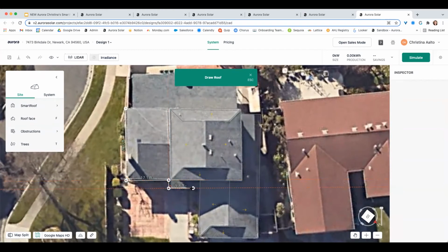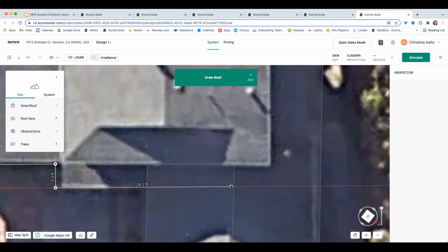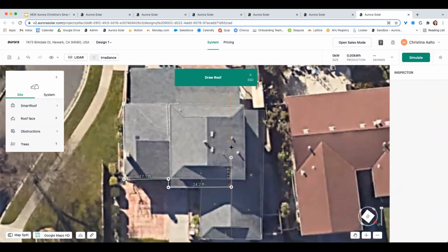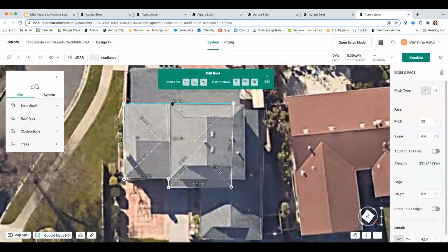And what we want to do is merge so that this is going to overlap with this garage. And I'm going to come over here and place this node right before that ridge line. And now we can bring this back up to about there and seal it up in the back. I think we want this line in just a touch and right about there. Okay, cool.